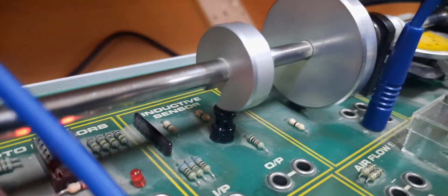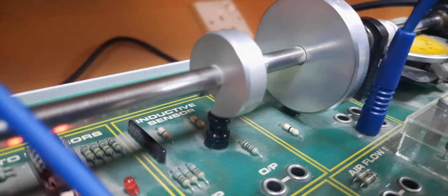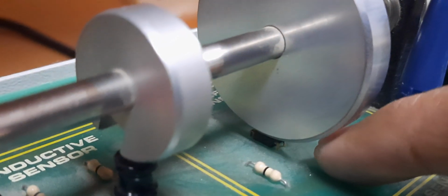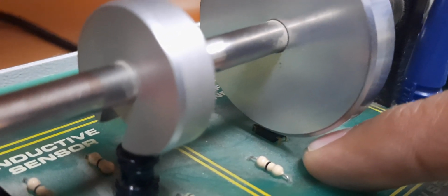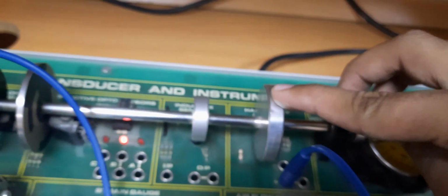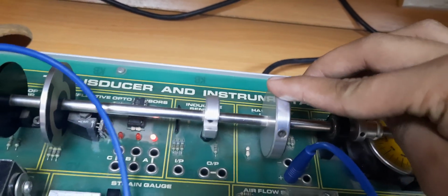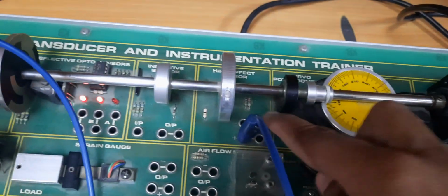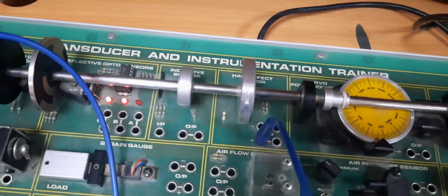The Hall effect sensor has the metallic disc that will be beneath this circular disc, the black one. This is the disc. Basically this is the IC containing that disc, and the magnet is mounted here. This is the magnet. So on one rotation, the magnet will cut the region 1 time, and so the voltage will appear between the negative and positive terminal 1 time.